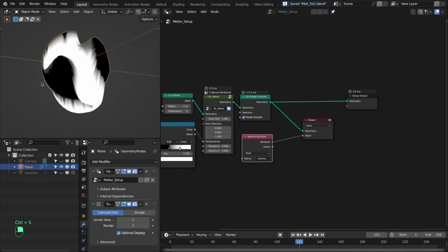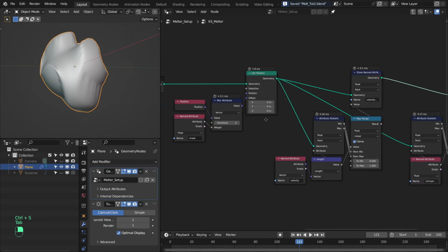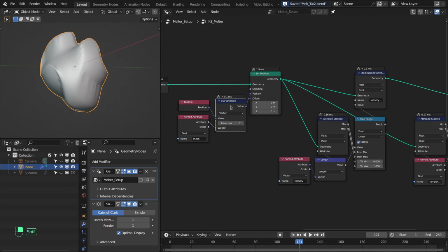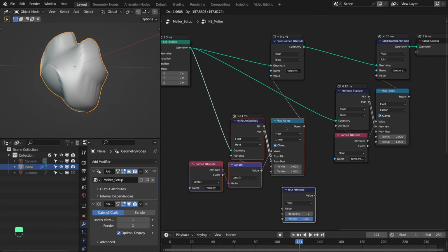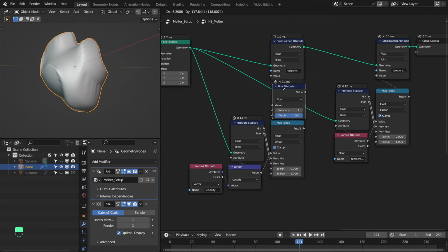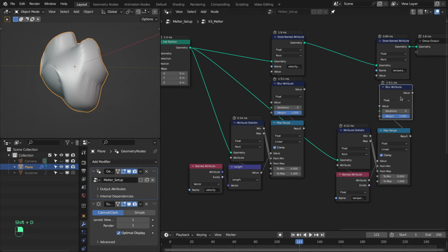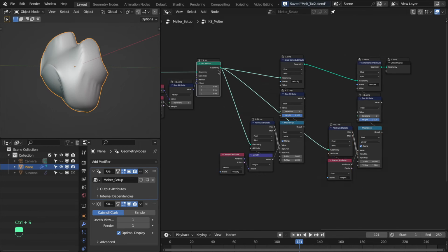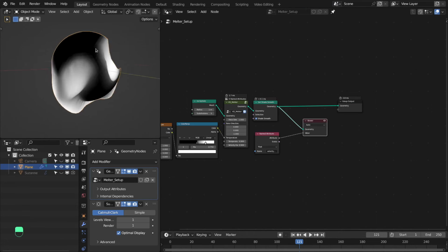So this is the velocity mask, and if we add the blur node we can smooth that mask. Change this to a float. Let's move this down, so let's blur by 3 times and also blur the temperature mask, so that will remove the sharp transitions in the velocity mask. See, we have this smooth velocity mask.